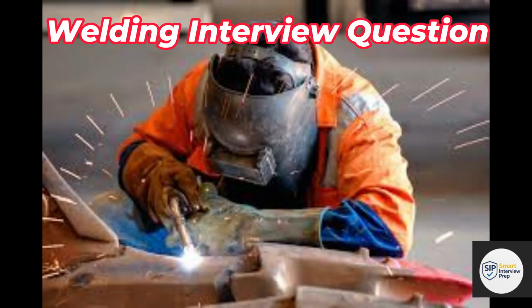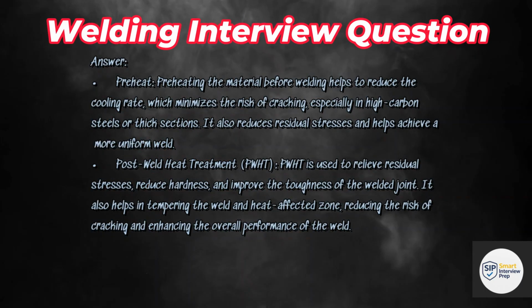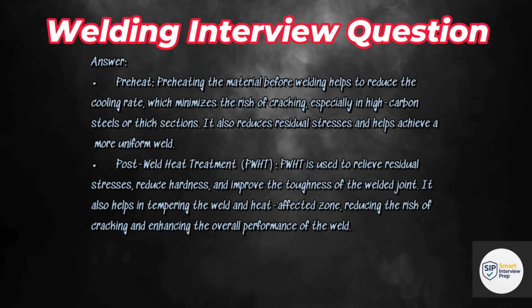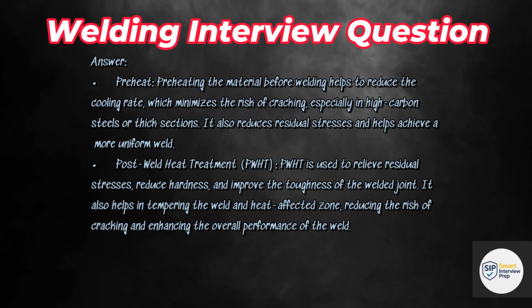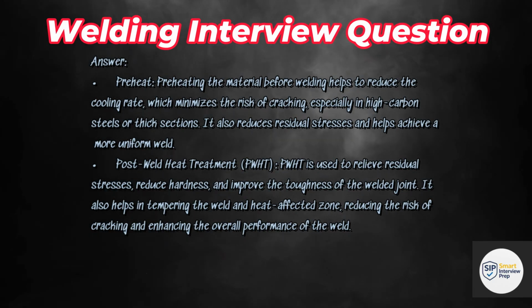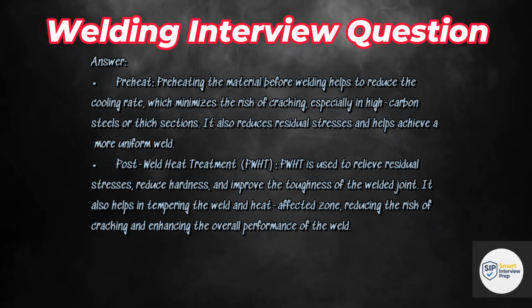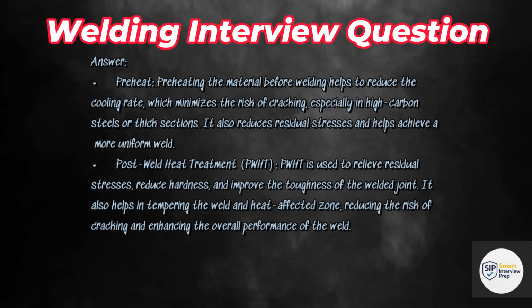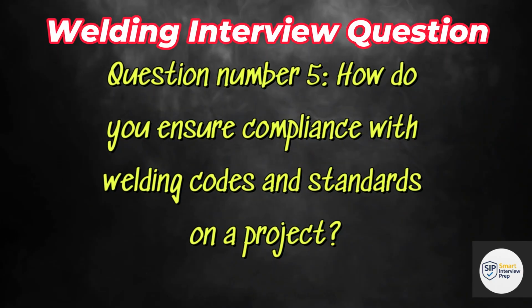Post-weld heat treatment, PWHT. PWHT is used to relieve residual stresses, reduce hardness, and improve the toughness of the welded joint. It also helps in tempering the weld and heat-affected zone, reducing the risk of cracking and enhancing the overall performance of the weld. Question number 5.